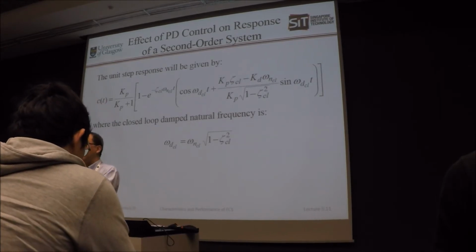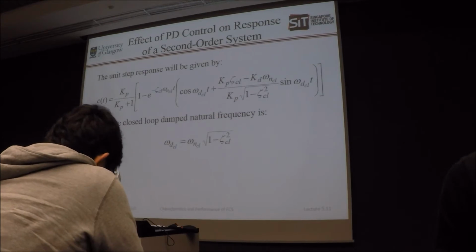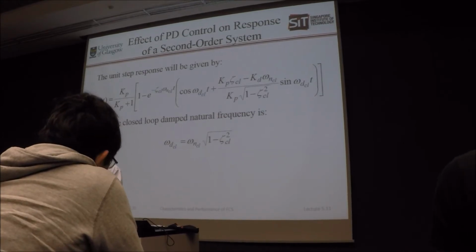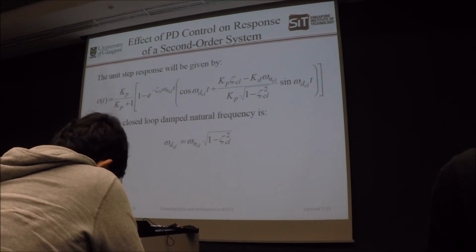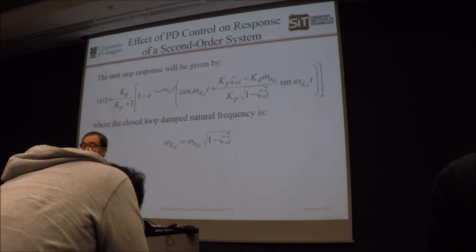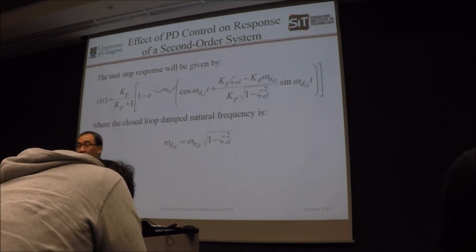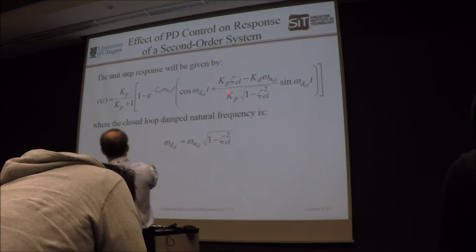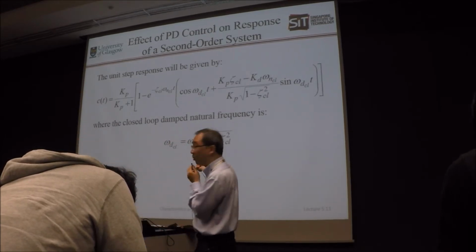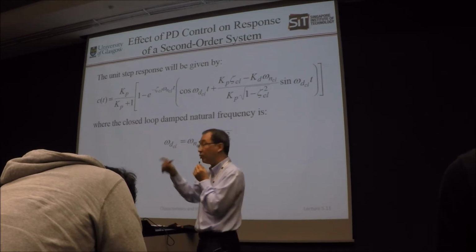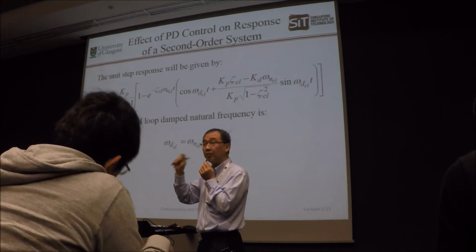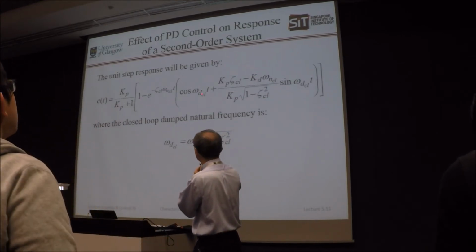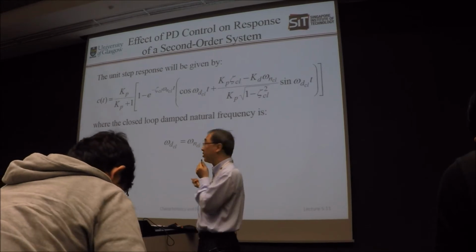So what you need to do is, based on a problem, you work out from the transfer function, and then you do an inverse Laplace transform. When you set your R(s) equal to 1 over s, and then you do an inverse Laplace transform, you work out the two terms, right? e to the power of alpha t, and then also your zeta omega n and so on, this omega d term. Okay, so you actually have two terms. You have this term basically controlling your decaying exponential. So this is a decaying exponential. This is basically your oscillatory frequency.